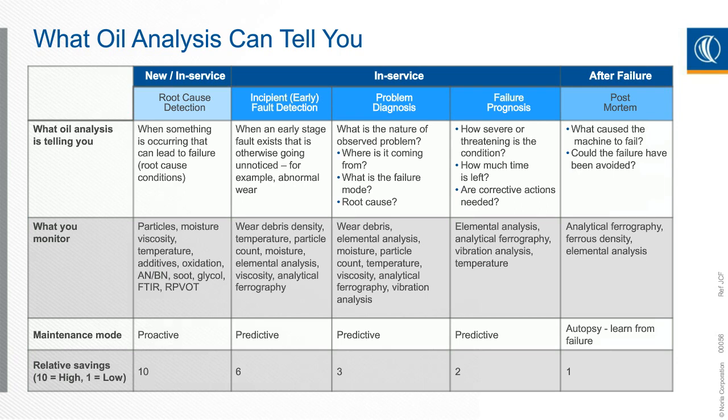Or potentially, let's say a machine fails, unfortunately, catastrophically, you can still do something with oil analysis through a post-mortem analysis. Meaning, if that machine were to fail, whether you knew it was coming or you didn't, you want to be able to hold on to that oil in that machine. Let's say it's a gearbox. Hold on to that oil and see if you're able to extract information.